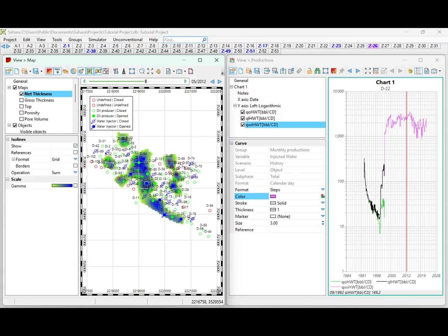Some other models will need more equations. For example, for Buckley-Leverett you will need the Corey exponents, so you will need to have that information as well. You will need to have an understanding of your permeability and relative permeability curves as well.